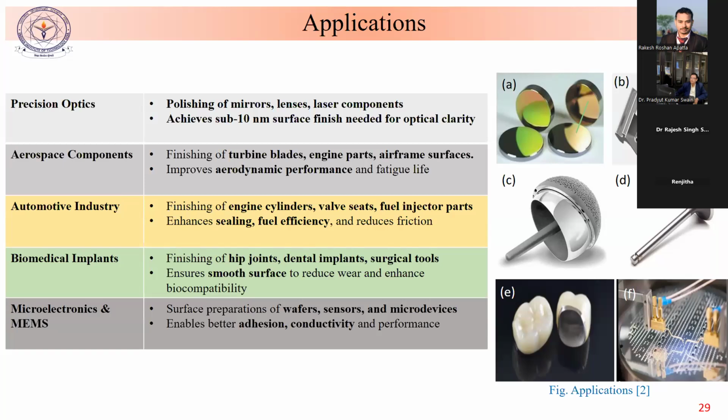During operation, if the diameter is just the diameter of your hair, it can break anytime. And we have to make an array of pins, let's say 20 by 20 pins. If one tool breaks, then we have to start the whole process again, because we cannot insert another tool and continue. The whole program is one program, and we cannot do it by part programming. That is again one of the issues.